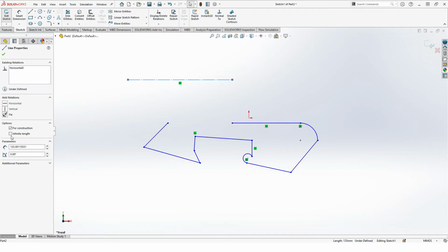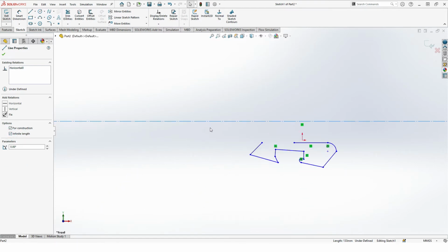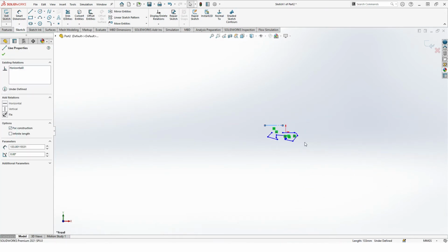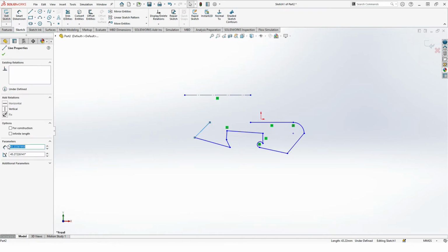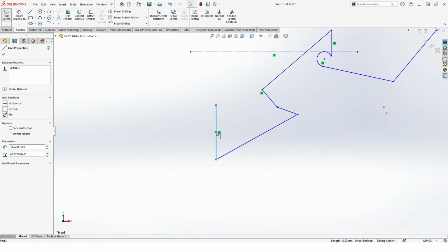If we change to the infinite, if we click the infinite, so see the line is changed to the infinite line. Okay, so this is also the way, just click the line and we change the option for construction infinite line. This is this line, if we want to make the vertical, just click this, the line will be vertical.